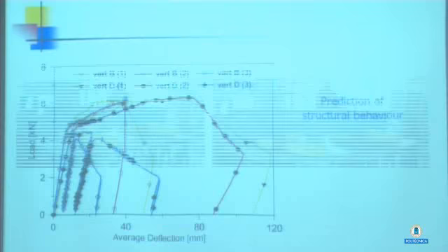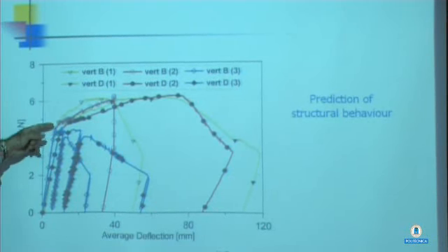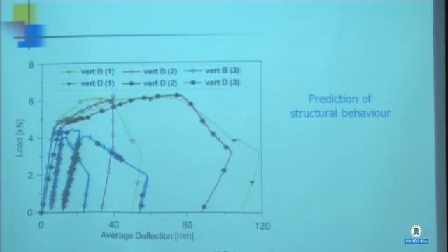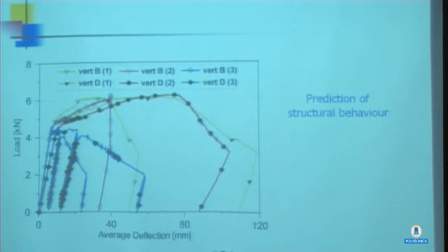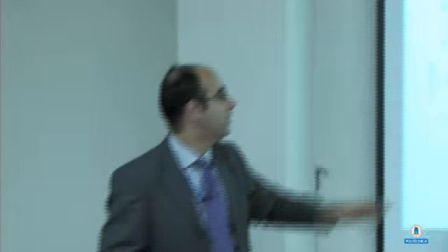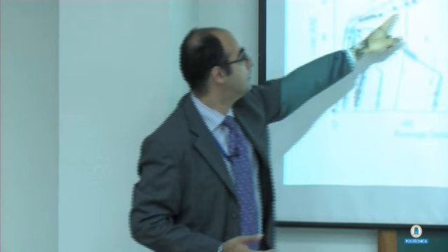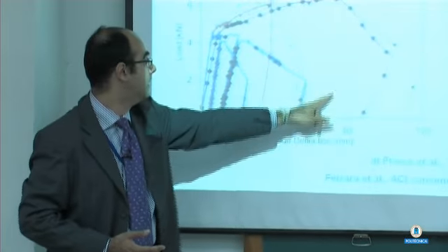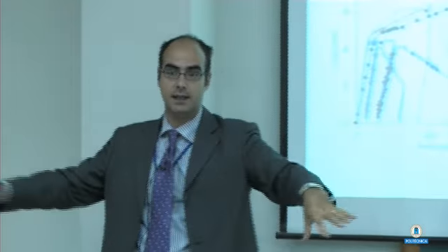You can see there the remarkable ductility of that element under the loads, and this is the performance, which also shows these were cast with some control of the direction of casting. These were cast randomly. So what we observed at the scale of the small specimen also reflects to the full-scale element. You have a higher capacity, but most of all, you have a higher ductility here in the mid-span section compared to this case, which was cast from the center and allowed to spread radially.